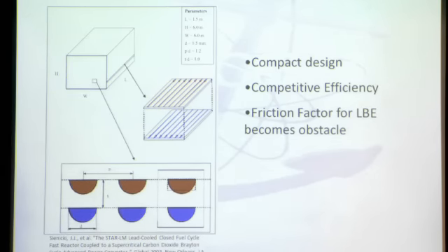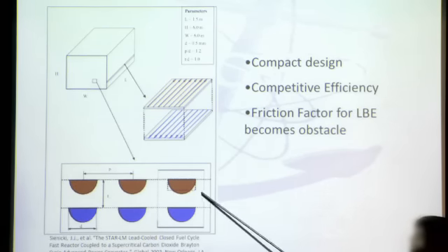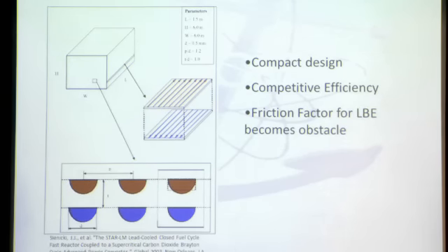And this is a quick diagram of how they work. Effectively, they're plates with coolant flowing in different directions, and they have semicircular channels on the different plates. One fluid flows one direction, the other flows the other. In these heat exchangers, it's going to be supercritical CO2 in both directions, so we don't have to worry about the different sizes. With the lead bismuth eutectic, we had to worry about having a larger channel diameter to ensure that the flow was appropriate.